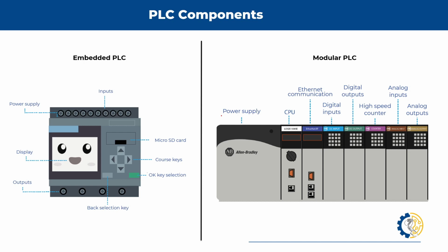So that same PLC can control process one for the year that it's being installed and process number two for next year. That's why you purchase the cards independently or separately. The embedded ones are used for smaller applications. Yes, robust, but not as robust as mid and top tier.